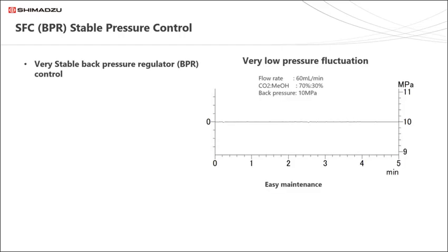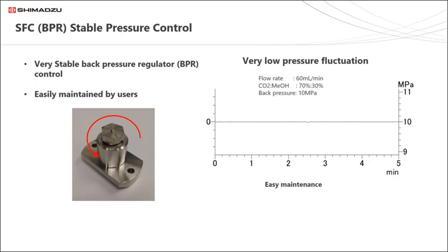Back pressure control is the Achilles heel of many SFC systems. With this new low volume, easy to maintain design, stable back pressure control is achieved and maintained, as you can see from the flat pressure trace.